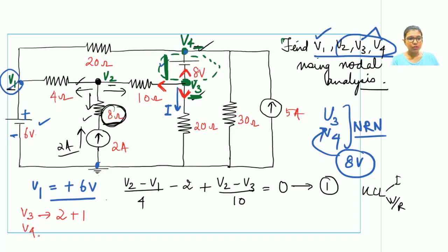Likewise, find out how many branches are connected to V4. This is the first branch connected to V4. Over here, there is a 0 resistance path. So one might say that this is the second branch. However, since this is a 0 resistance branch, you cannot consider this to be a connecting branch. You have to eventually reach the ground. One cannot write the KCL equation for this branch. Why is it so? Because this node is at a potential of V4.